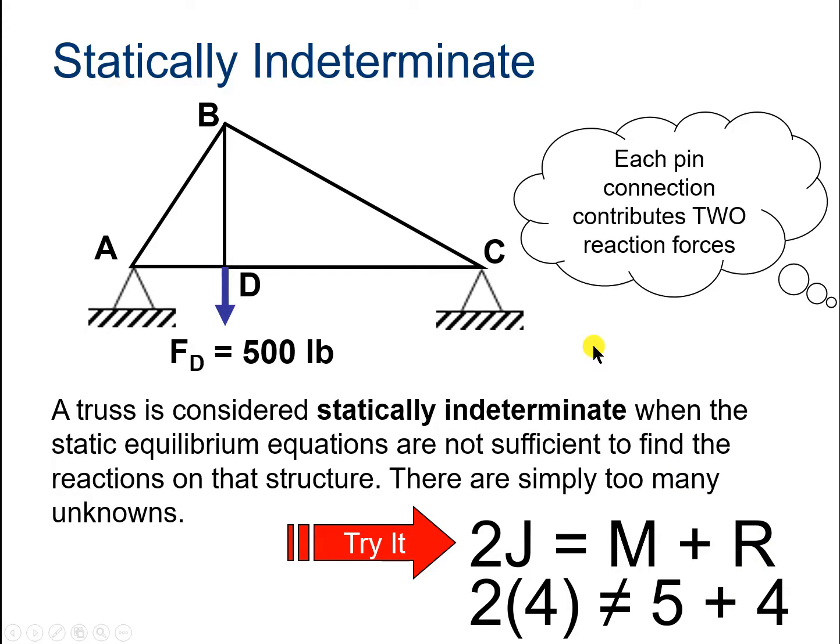The way I like to think about this is, if you're making a sketch in a 3D CAD software program, or maybe any CAD software program, you can over constrain it, in which case you're not able to continue to specify dimensions, because it's already so wound up, so to speak, that it can't really move and do anything.